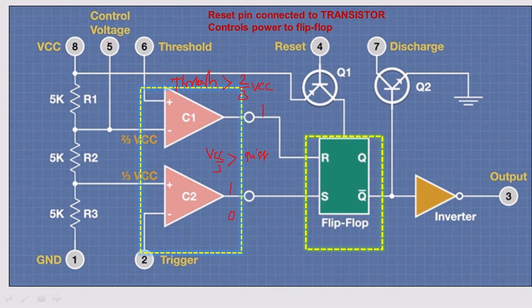That is the need of this control voltage terminal, right? To vary the time electronically by providing the modulation voltage to the control voltage input terminal. If you are not using this terminal, it is recommended to connect some capacitor to it, to avoid ripple from the supply or noise. If you are not using this, it should be connected to some capacitor. Okay, so I hope you understand.